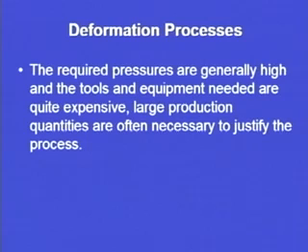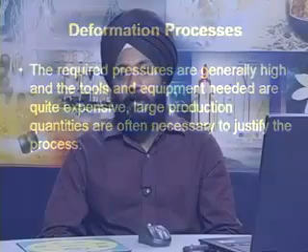There are certain processes like hand forging, which is not that expensive, but wherever we go for die arrangement or punch arrangement, the material of the die, the size of the die, the intricacy of the product often necessitates a very good die, so that whatever is the shape of the die, whatever is the surface finish on the inner walls of the die is replicated on the final product.